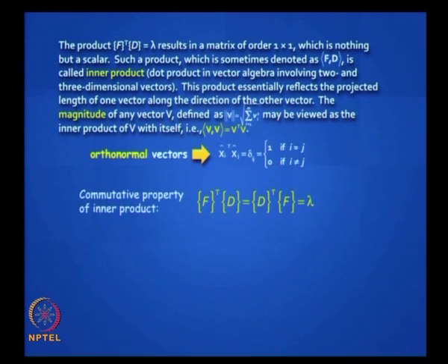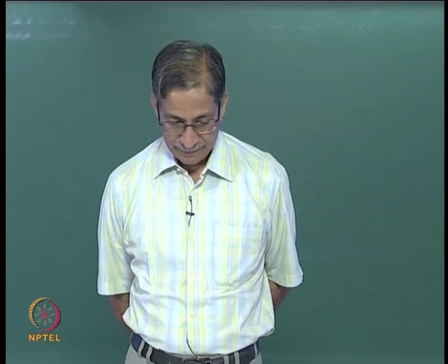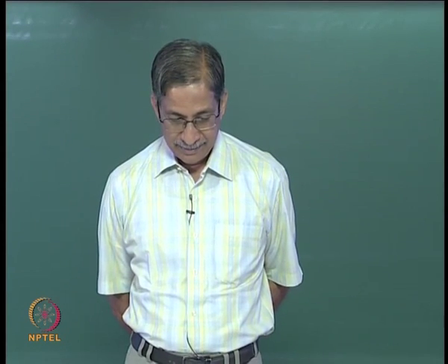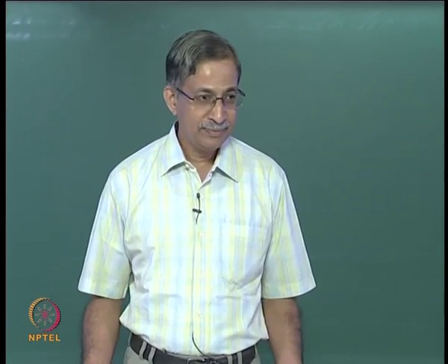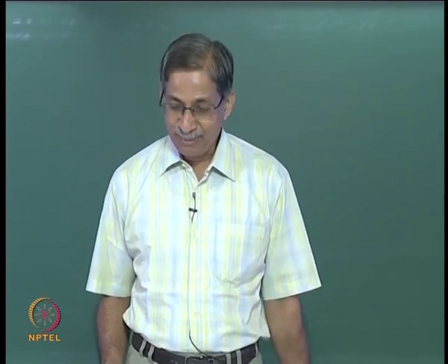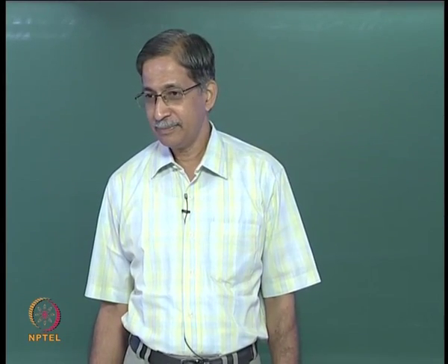You can calculate work either by converting the force vector to a row vector or the displacement vector to a row vector, you get the same answer. And if you introduce the relationship between force and displacement through the stiffness matrix, you can arrive at an interesting conclusion. Can you tell me what that conclusion is? See, the first is a commutative property, the second is a stiffness relationship, it is a law. If you plug in the second property to the first property, what can you end up proving? K is, yes, that is really good.